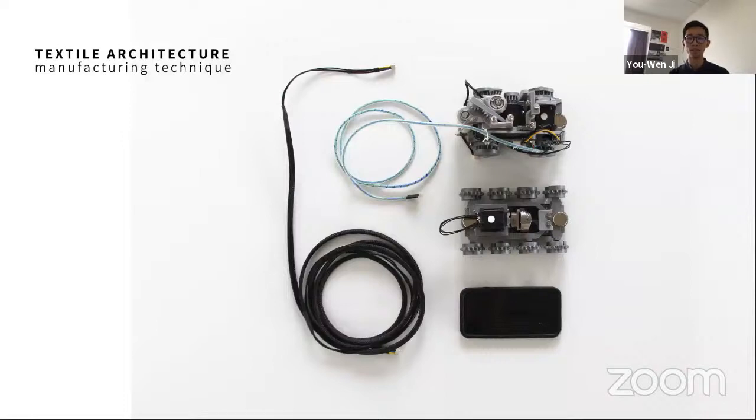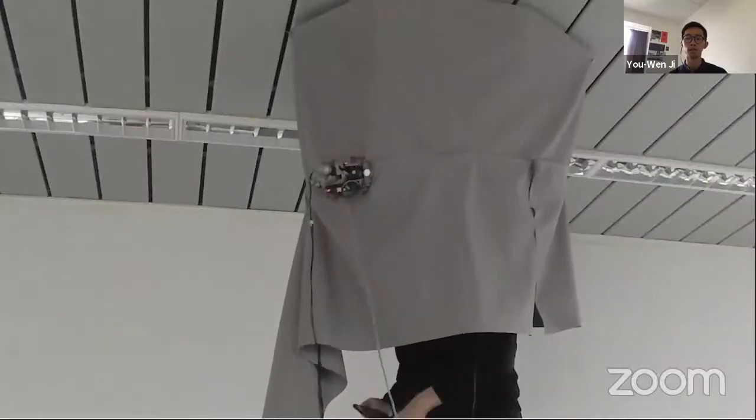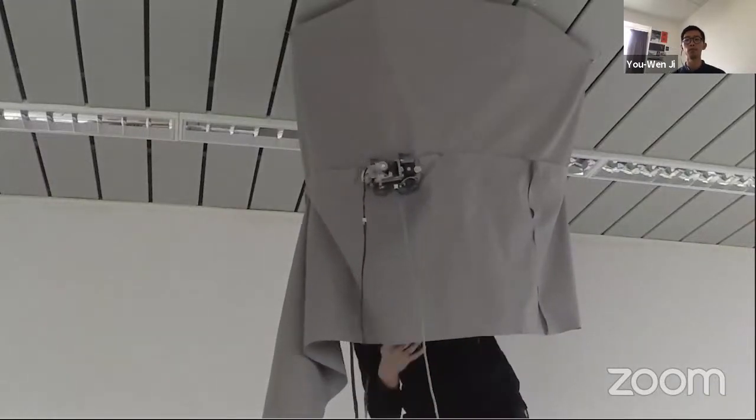Finally, we can start demonstrating, and these are all the ingredients you need. In demonstration 1, I try to prove the spiral pattern method through a stitching bar and manual control interface. Also testing the minimum radius of the surface curvature, the diameter is set to 60 centimeters, 4 times the robot body. Then the result of the demonstration is proving the spiral method could be done by